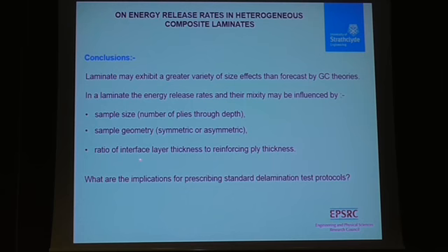I've not shown it here, but in the paper I show some results to show that the ratio of interface layer thickness to reinforcing ply thickness also influences the energy release rates and their mixity. And I finished off, as I promised, with a question: what are the implications of all this for developing standard protocols for doing delamination tests?